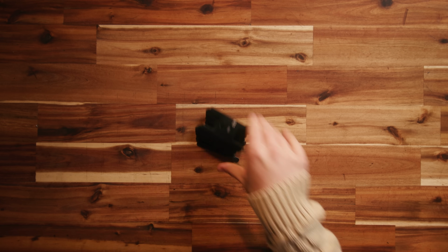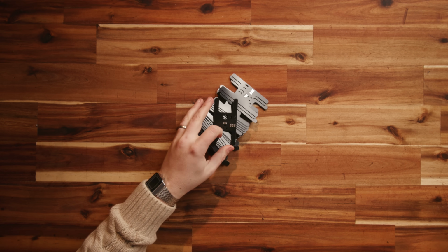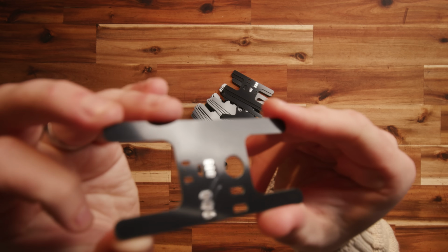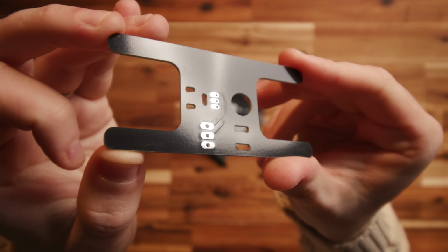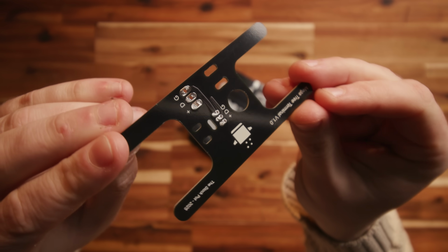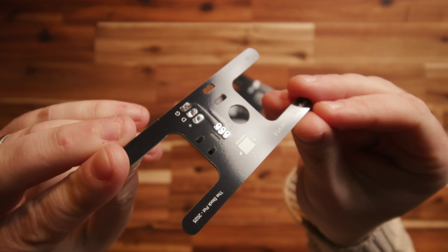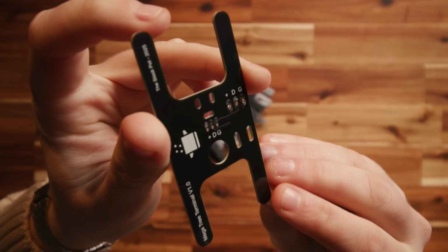I still want to avoid having to make hundreds of wire-to-wire connections, so I made these little H-shaped PCBs as well. These each have solder points for the pixel string, as well as an attachment point for a pigtail. I also added these 12mm holes for our tensioning solution.